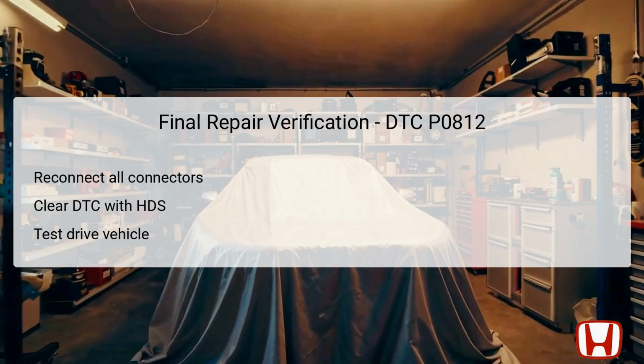new diagnostic checks. Subsequently, start the engine and initiate a test drive, making sure to shift into reverse at lower speeds of below 3 miles per hour for a duration of at least 2 seconds. Then increase speed and drive over 3 miles per hour for 2 seconds more.